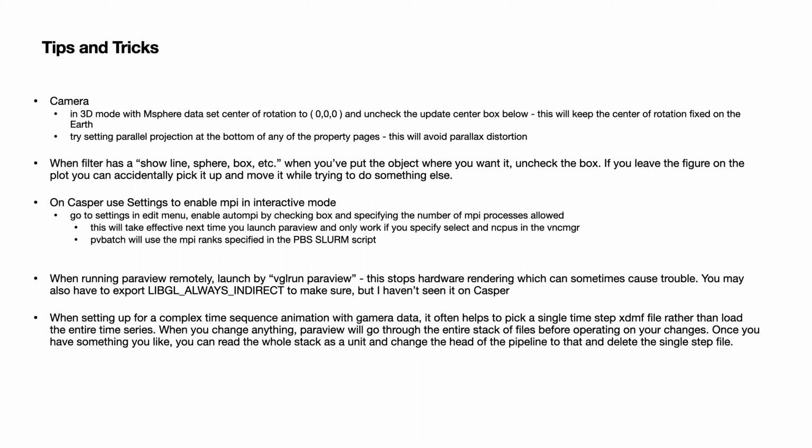It helps sometimes to, instead of just running Paraview as the command, run VGL run Paraview. It stops hardware rendering, which sometimes interacts badly with the virtual screen, so you can end up with situations where nothing shows.